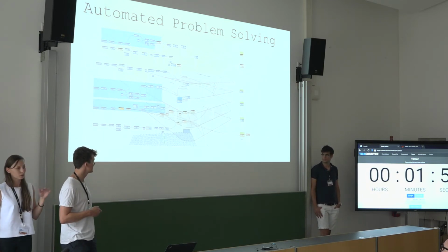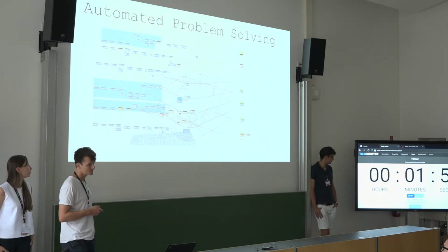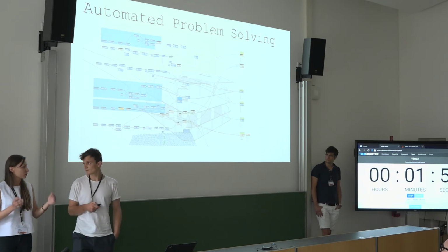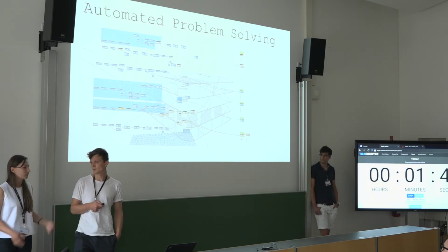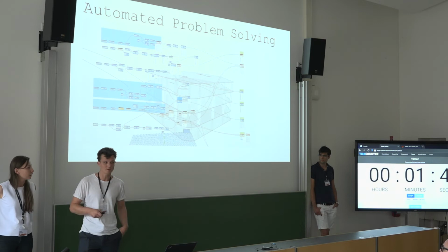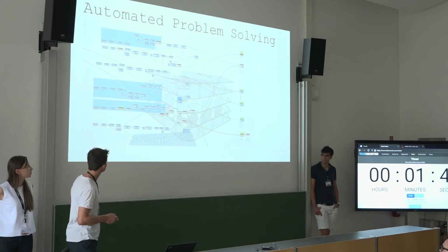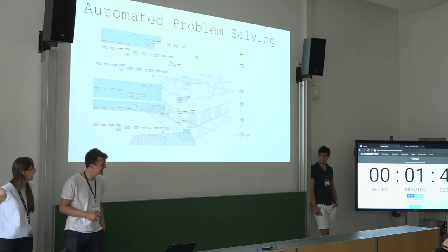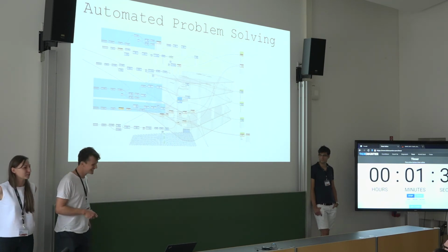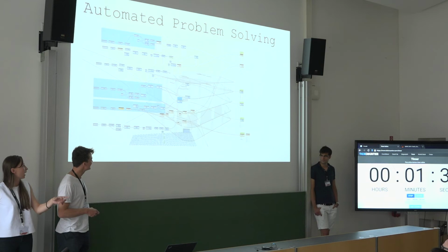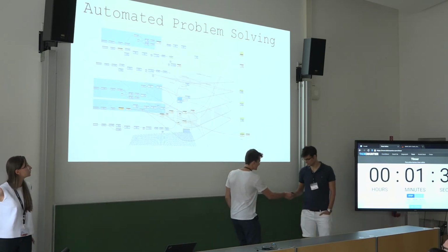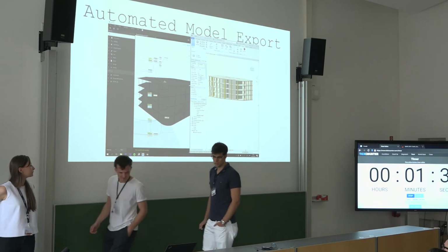We had some general troubles with the axes because they were somehow split into three parts. But it was the problem of our model we used. No, it was a transfer problem, basically from Revit. In Revit there was one axis line, and in Dynamo it transferred to three single lines.